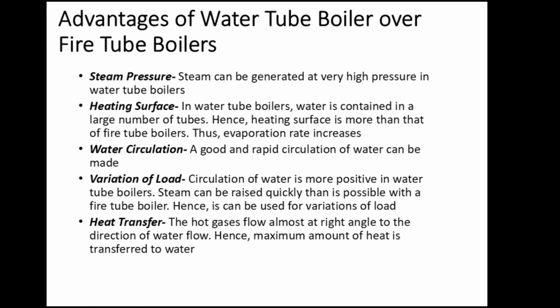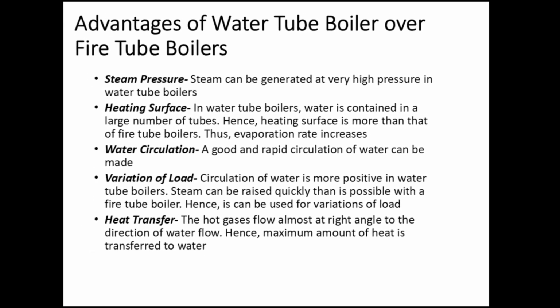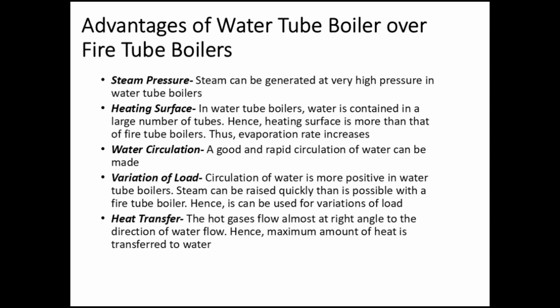Advantages of water tube boiler over fire tube boilers, continued. Safety boilers. Bursting of one or two water tubes does not affect the boiler very much with regard to its working. Hence, water tube boilers are sometimes called safety boilers. But bursting of flue tubes in a fire tube boiler causes serious problems.